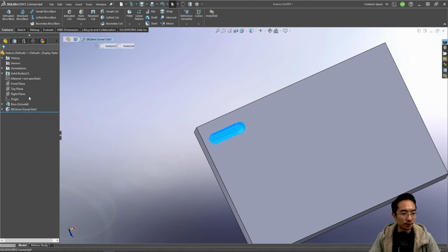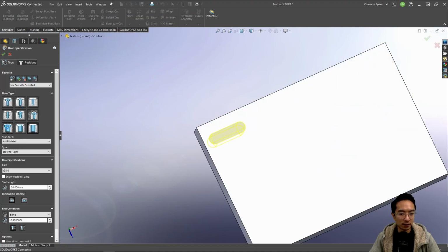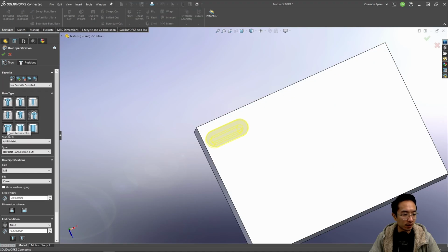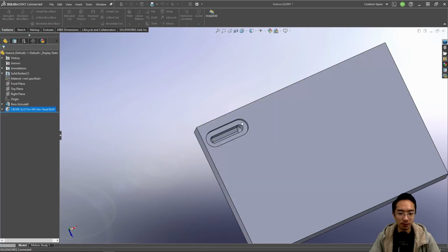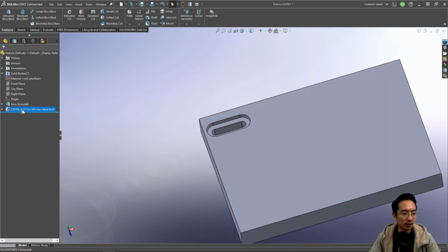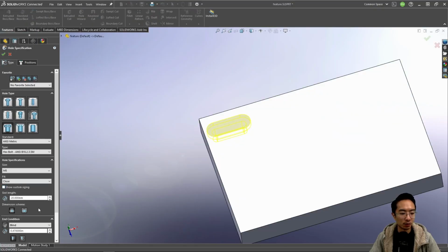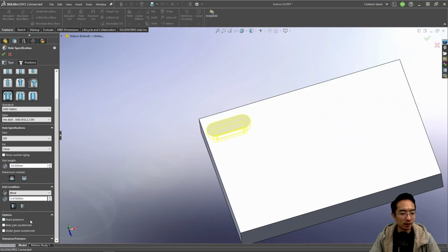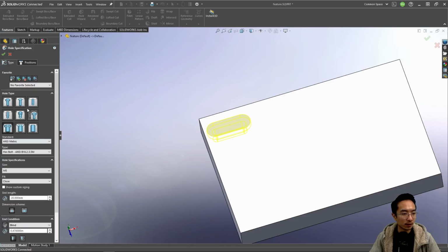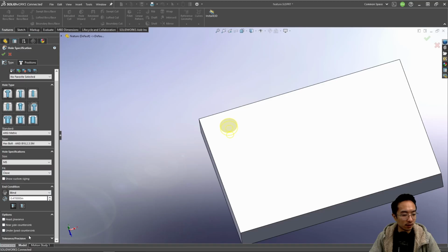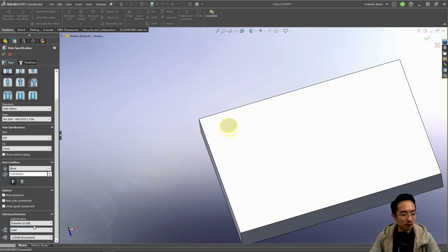Okay. So there's a bunch of other stuff, right? You could play with this. This is called the counter bore slot. You can see how that looks. And then sometimes you may actually want to configure your head. So you could go in here and we'll actually look at this one. It's a little bit easier to see, but you could see there's different tolerancing and precisions you could have.